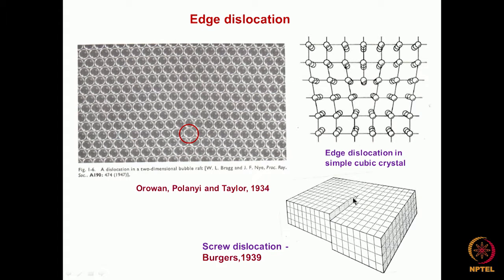Okay. The dislocation line is going from one side to the other side of it. And the defect which has been introduced here also, if you look at it, the step is coming in the same direction as that of the line direction. So these are called screw dislocations.